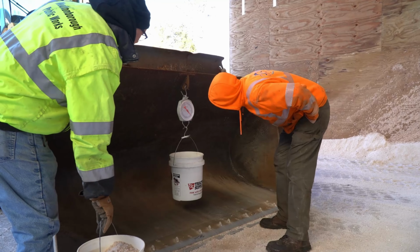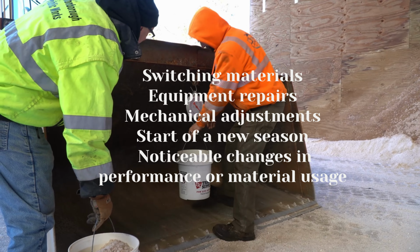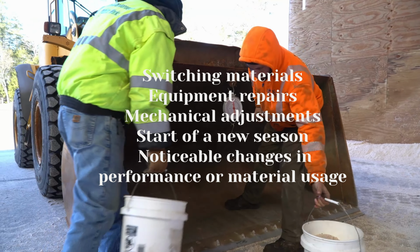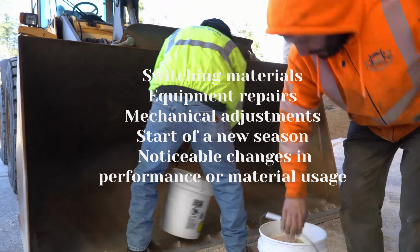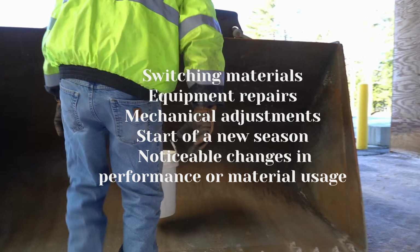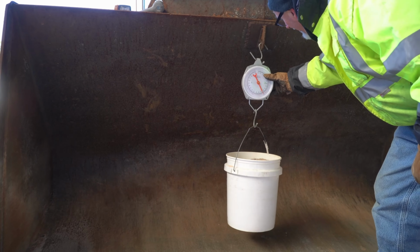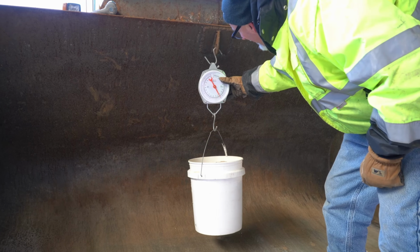Recalibration should be performed whenever conditions change in a way that may affect material flow. Examples include switching materials, equipment repairs, mechanical adjustments, start of a new season, or noticeable changes in performance or material usage. Any condition that changes how material moves through the system can affect calibration accuracy.